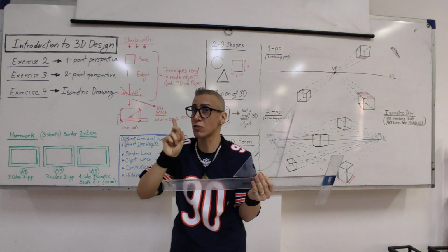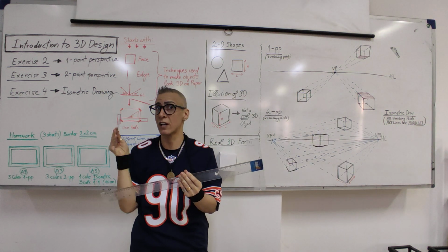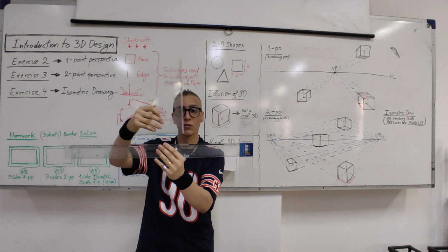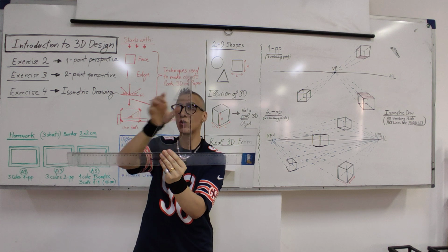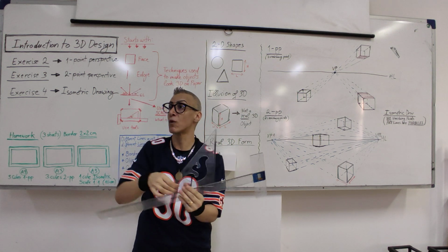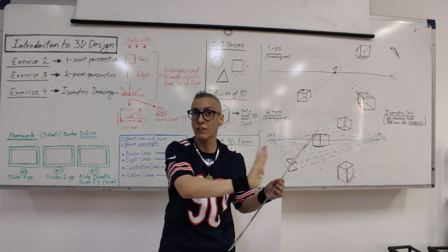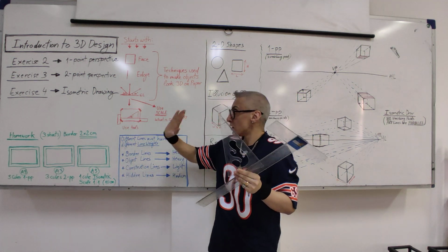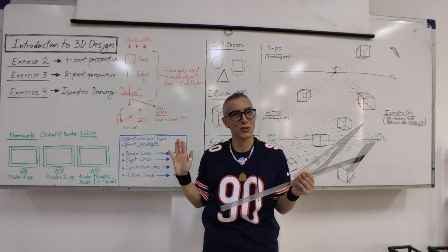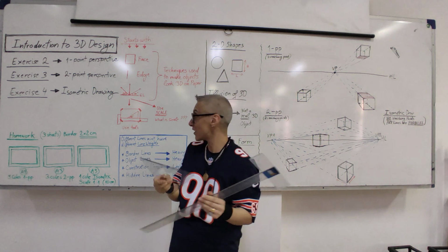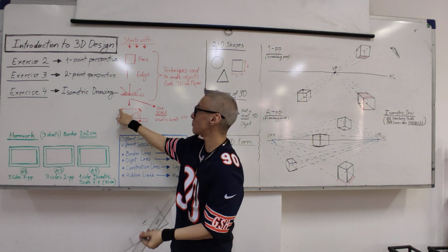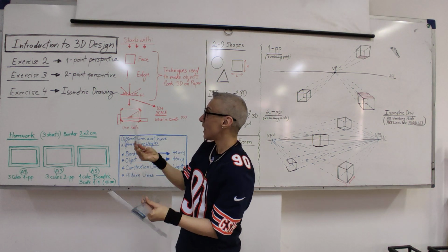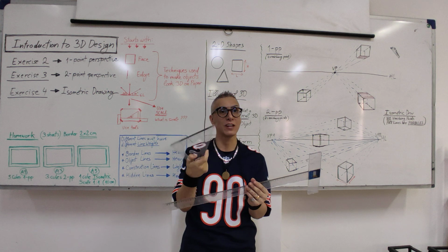Be careful not to do it freehand with the ruler like this, where one line is like this and one line like this. No, you put the T-square, you draw straight, beautiful lines while the paper is fixed on the table, okay? With the isometric, for sure you need to do it, because otherwise it will be a disaster. So you have your paper, I put the tape here, as you can see, the T-square you will put it, and you will need to use the 30-degree angle.